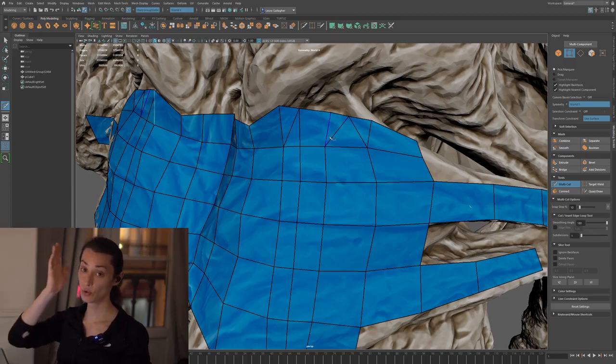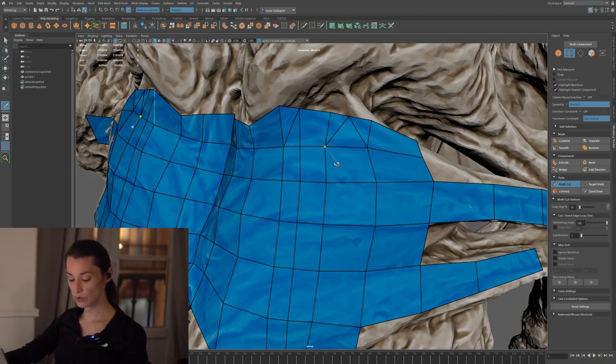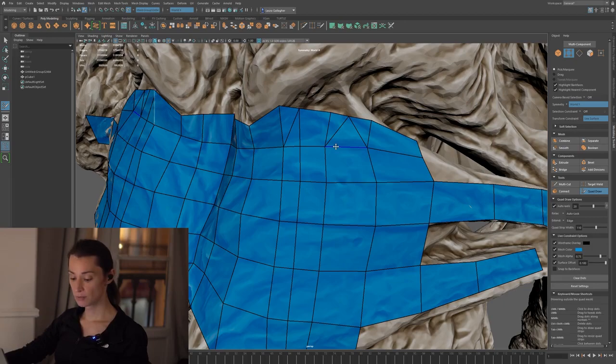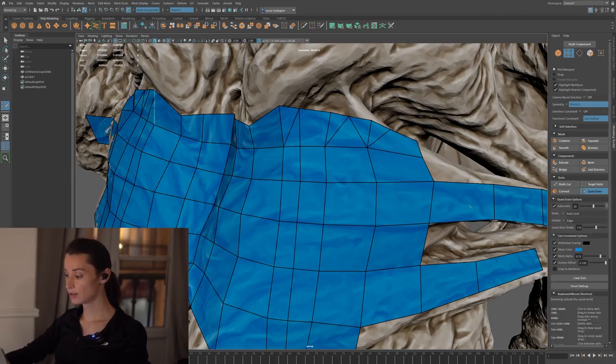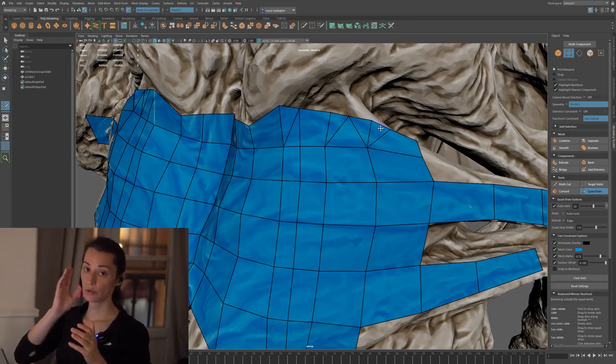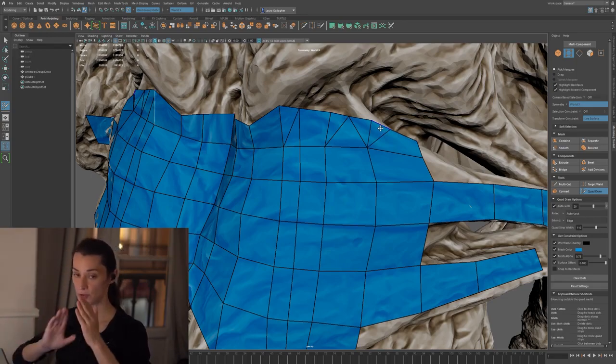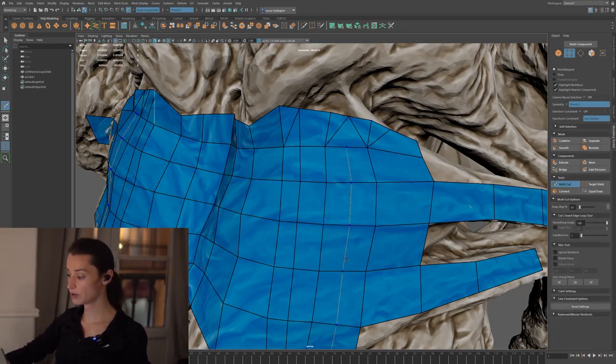And if you want to go back to Quadra, then you could, of course, just click on Quadra here again, or you could once more hold down Control-Shift, right-click, and go towards the top. So the same movement here. Which means that once you actually become very good with marking menus, you can go from Quadra mode like this into multi-cut mode somewhere, and then like this, go back within Quadra mode. So always Control-Shift, right-click, and go towards the top. If you do it in one single stroke, you can swap between these two modes very, very simply like that.